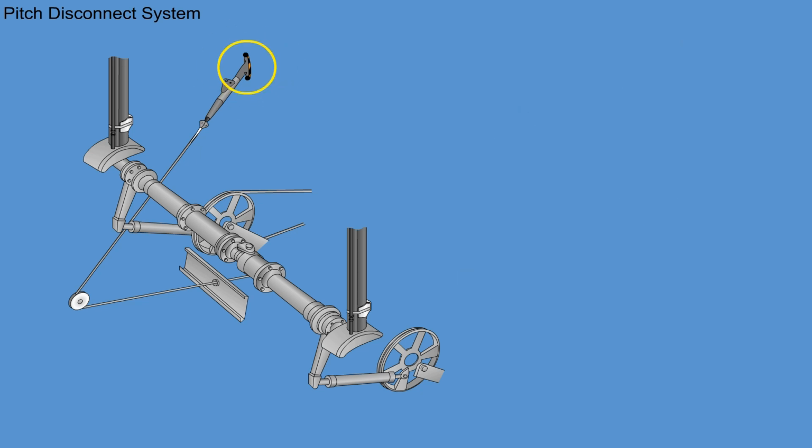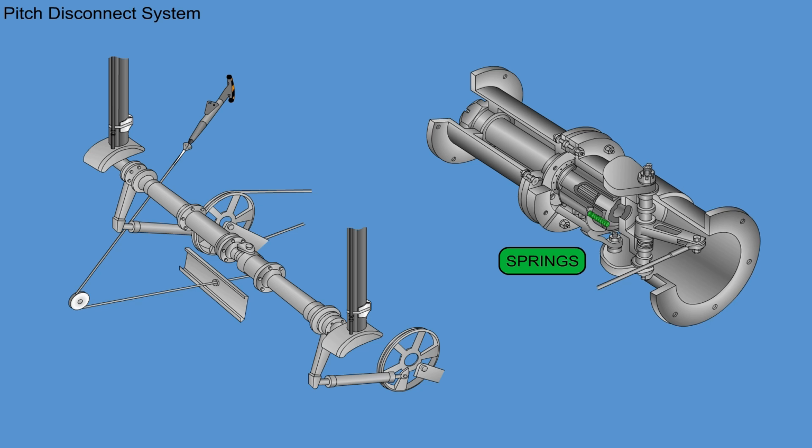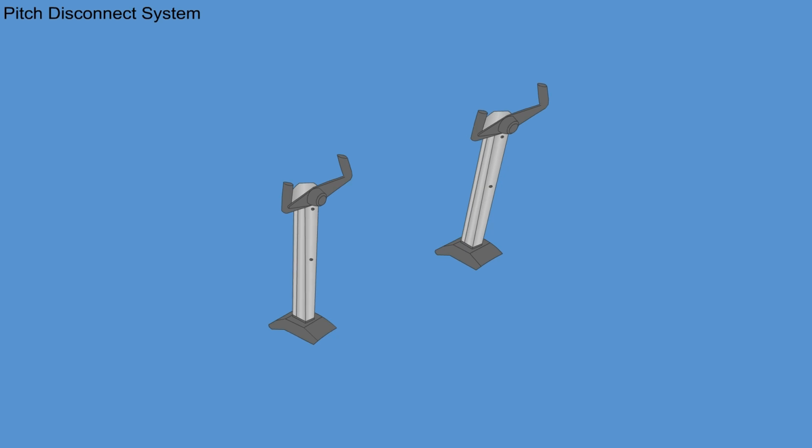Turning the handle 90 degrees locks it in this position. Turning the handle back 90 degrees and releasing the handle allows the springs to force the clutch to clutch plate. The clutch re-engages if the columns are aligned.